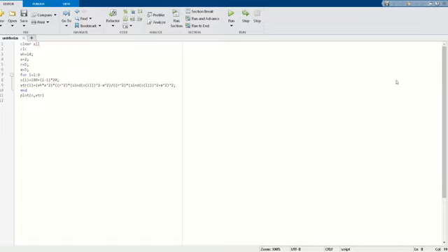With the help of a MATLAB program, we are able to study the tower shadow effect on a wind turbine. We have considered the following parameters: VH is equal to hub height wind speed, A is equal to tower radius, R is equal to turbine radius, X is equal to distance of blade origin from tower midline.